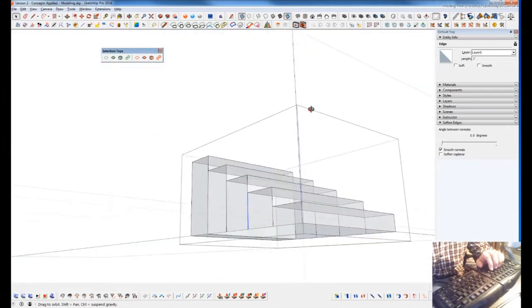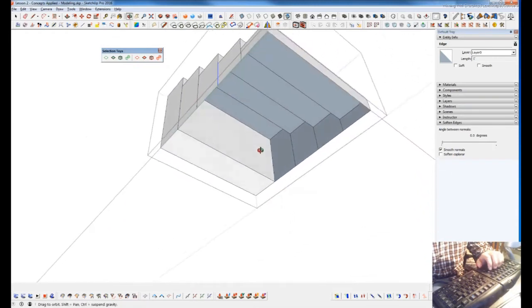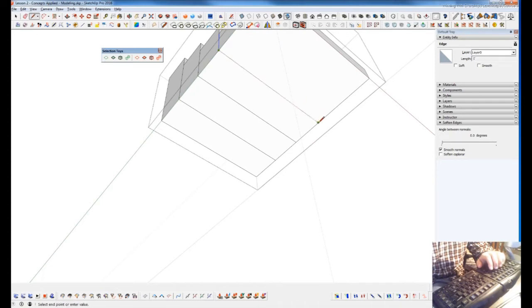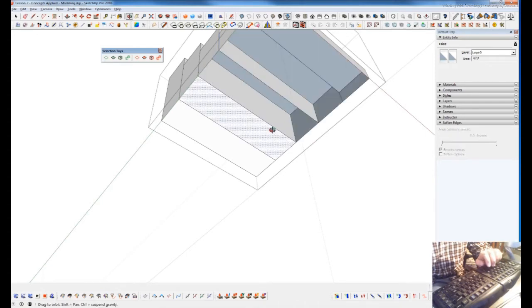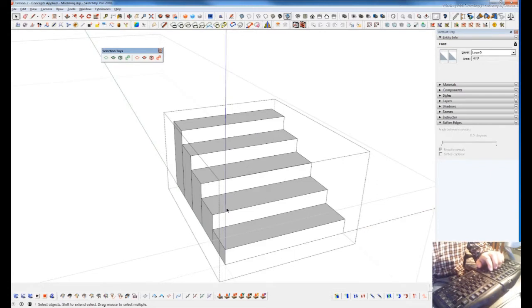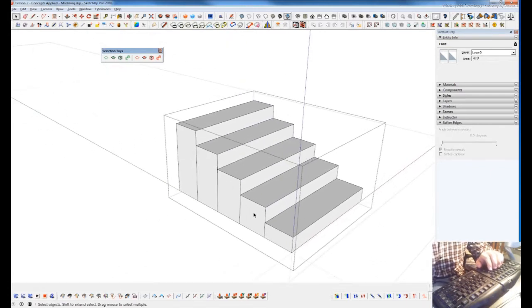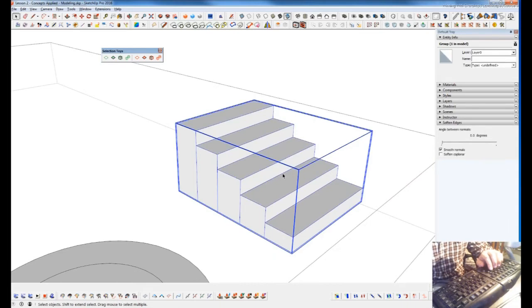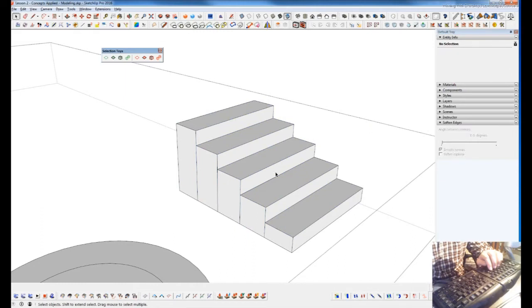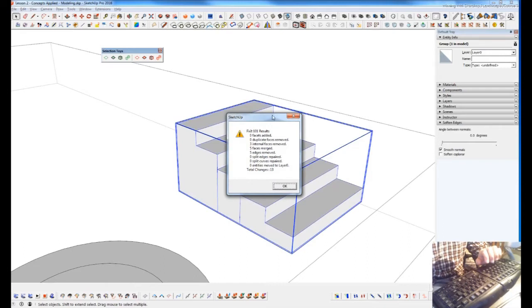So we go through, now we have some interior faces in there. But if I delete these, see we have some interior faces, we have these edges on the outside, so the cleanup work on that to get that to be a solid would be a little bit tedious. With this Fix-It, and it's in the right click option, but I have this set to Control-Alt-F. I could just do that very quickly. Again, Control-Alt and click something, Control-Alt-F.